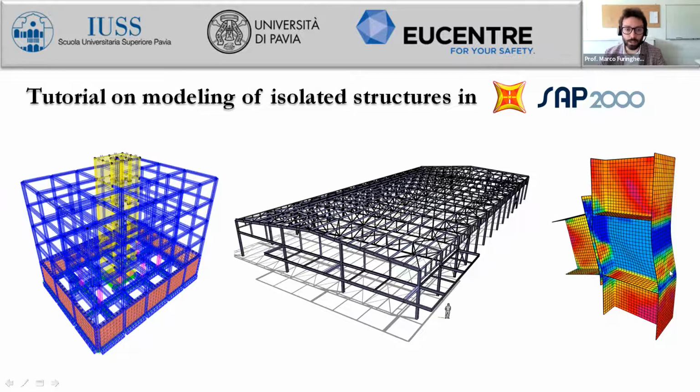this model, what I adopted was a model with 2D elements, because all the plates are meshed into shell elements. But the structure is three-dimensional, and I found a strategy because I had to perform a nonlinear time history analysis, but the overall structure was linear. I mean, the time response analysis I had to perform. And I found that there was a strategy within the software which is not the direct integration of the equations of motion, but the modal integration.